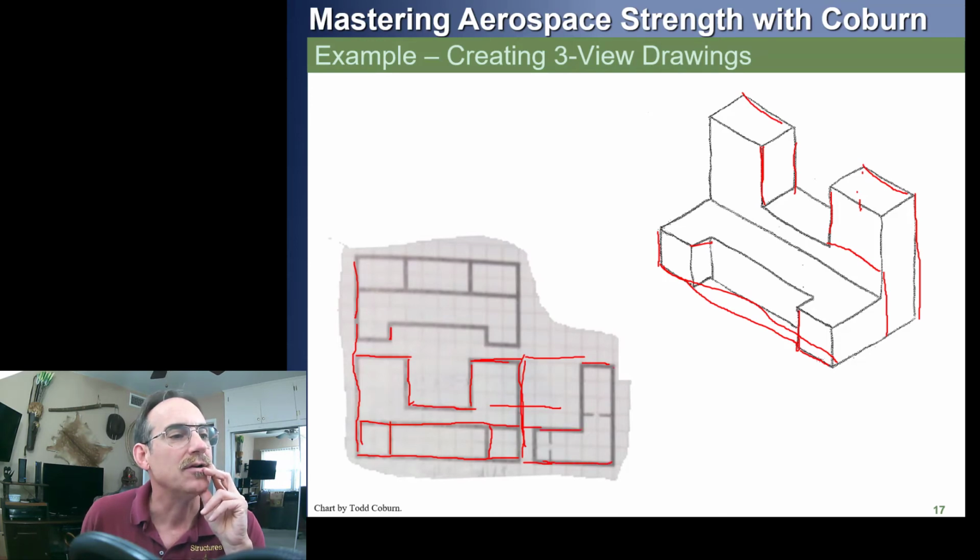We can draw the back of this part, the front of this part, and if we measure this dimension here, we see where this hidden line belongs. This cannot be seen from this edge. If you're looking this way, you have to look through this part to see that projection there. That's why this line is shown as a hidden line. And this is the same dimension as this, and now we have that. And then this one also can't be seen, so this is also a hidden line.